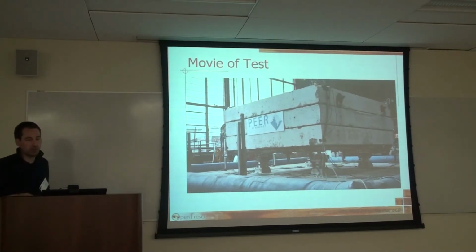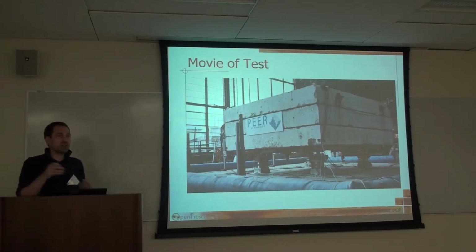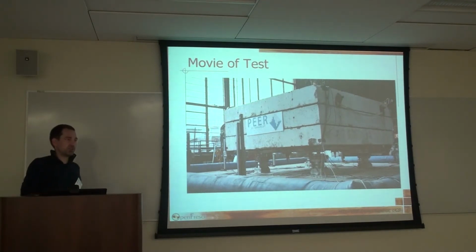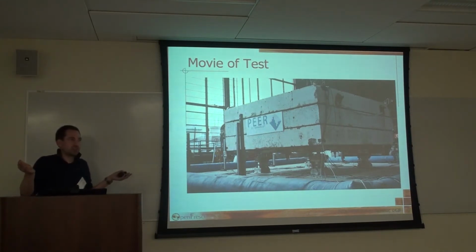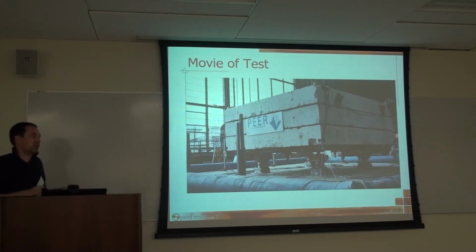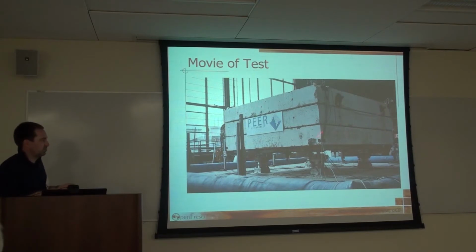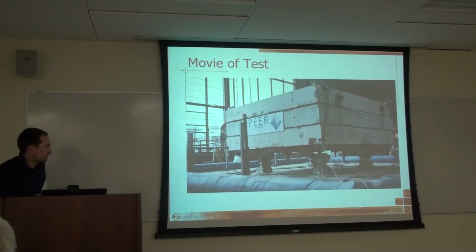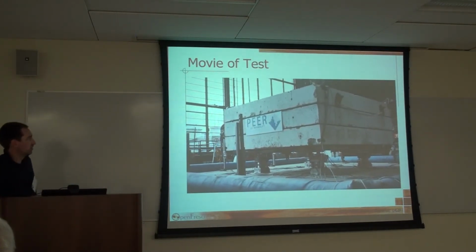The reason is because we also had some models, I didn't show it, that are not shear representations of a building, but actual flexural representations of a building. Especially on a tall building, obviously at the very roof of the building, you're going to see rotations. If you have a tuned mass damper on top of the roof, and you have rotations there, you really want to see what happens to the tuned mass damper, including those rotations. That's when it becomes important. And that's why when we run this test, you might see that the table also has the roll and the pitch.